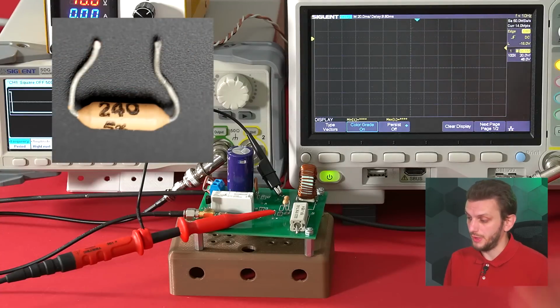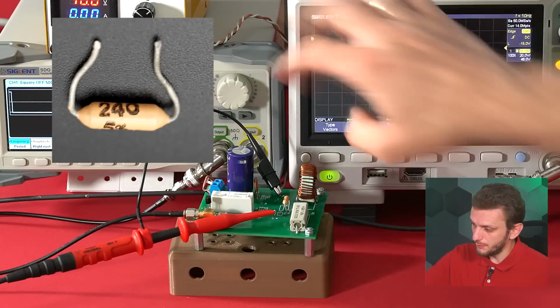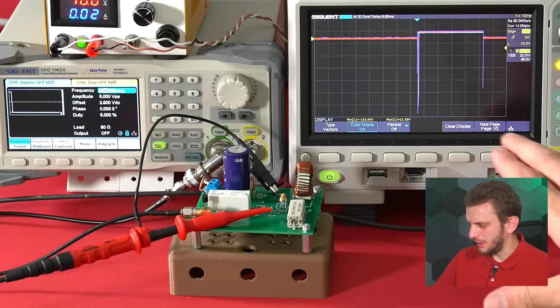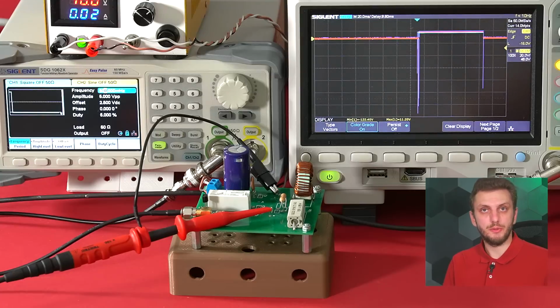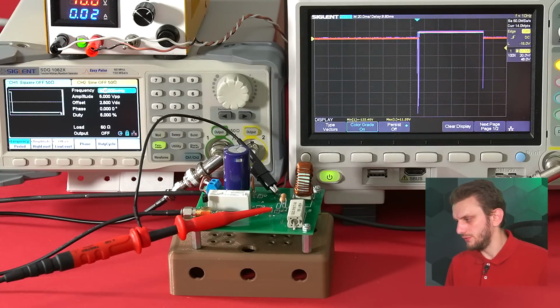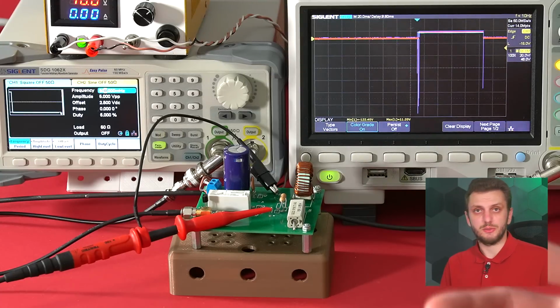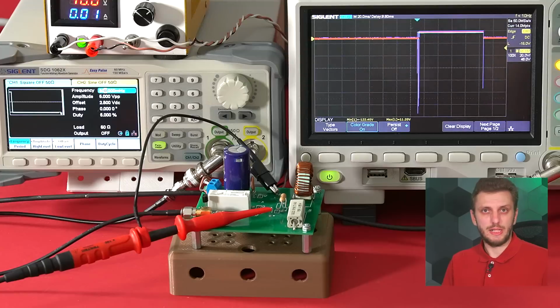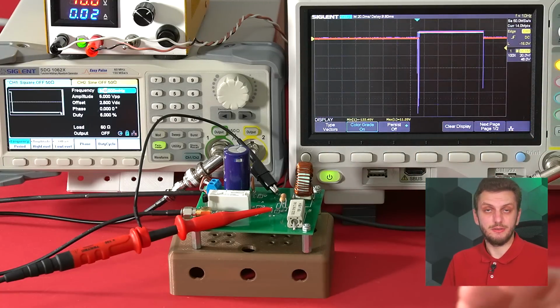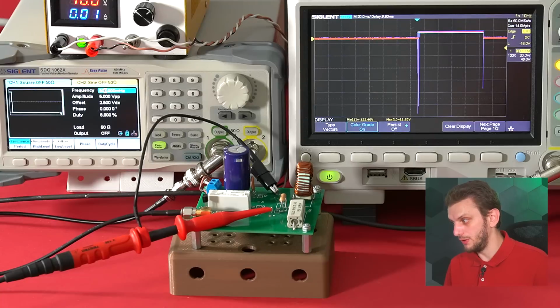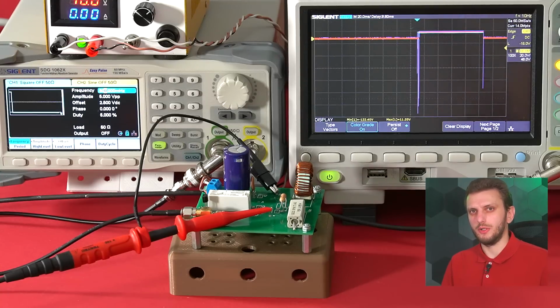So if we try with a resistor in parallel with the load, we see that it is clamping at around 120-something volts, so various different values depending on the pulse. But this is one of those cases where just because it works doesn't mean that it's reliable. Right now I'm using a resistor that is not specifically designed to handle high power pulses, so it will work, but it's not very sure for how long.